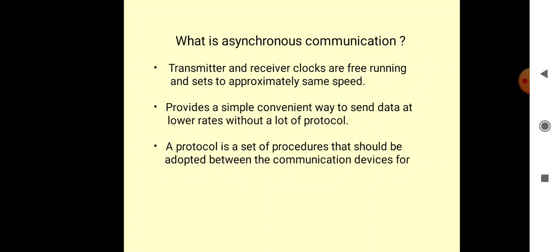This is all about asynchronous and synchronous types of transmission, and the need for the start bit and stop bit. We also covered the advantages of synchronous communication and the advantages and disadvantages of asynchronous communication. UART is a device which is a digital IC used to perform parallel to serial and serial to parallel data transfer. Most data transfers and operations inside the computer are parallel in nature.